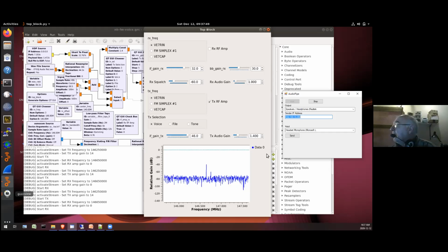Just getting my mic out here. If you watch the receive spectrum, it will freeze, because when the SoapySDR HackRF driver switches into receive mode, it stops sending any data on the receive path. And this GUI block here is on the receive path, so it stops getting signals. It actually appears to freeze. Now it's still actually running, but there's just no data for it to work.